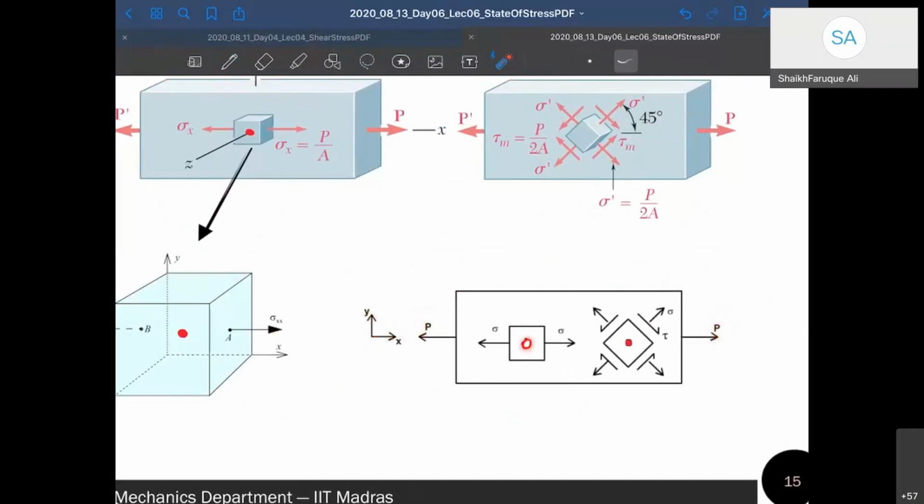So you point and point A and along its surface. So if this element, you can see this element is oriented normal directions, right? Normal XY direction. So this is going to be sigma. This is going to be sigma. There is no shear stress acting, right? I have not drawn any shear stress, so it's not acting on it. Now, if I make that angle a little bit inclined, let's say this theta angle. So this plane is also inclined. You see, my diagram of the plane is also inclined. So this is how you represent, the engineering representation, that the plane has now become an inclined plane.